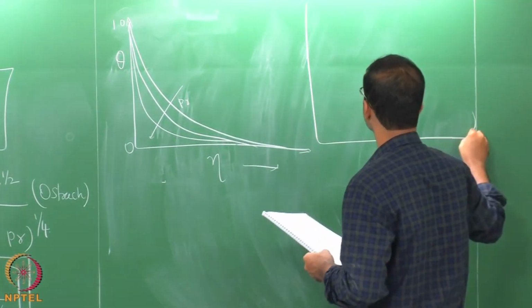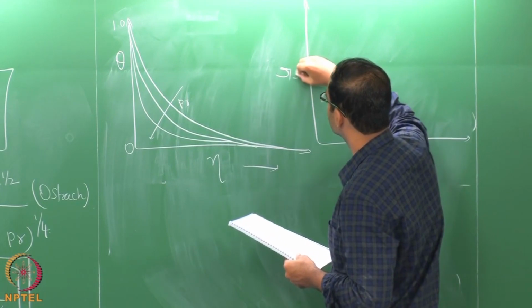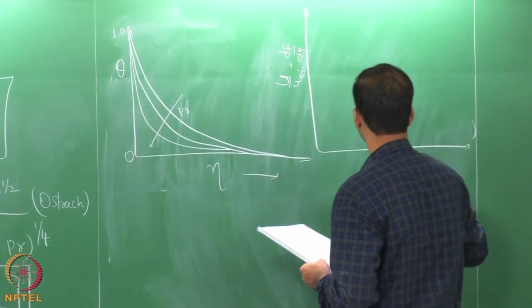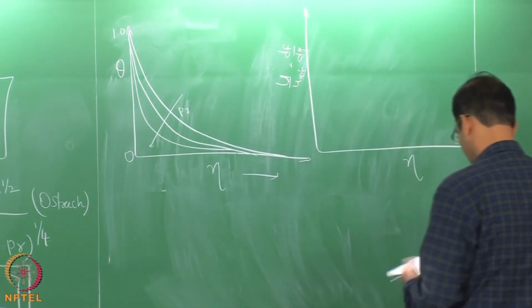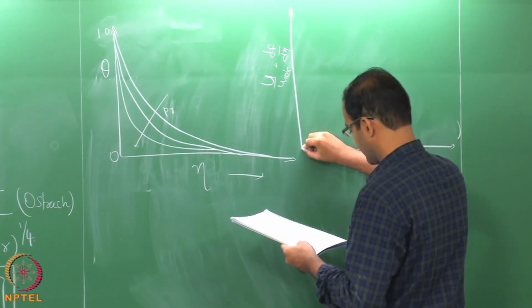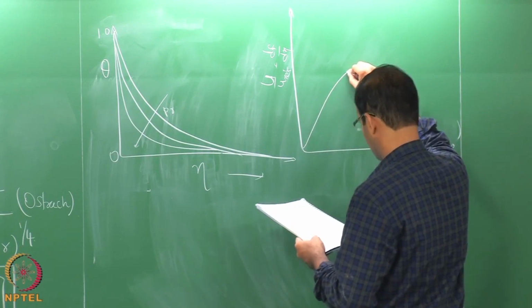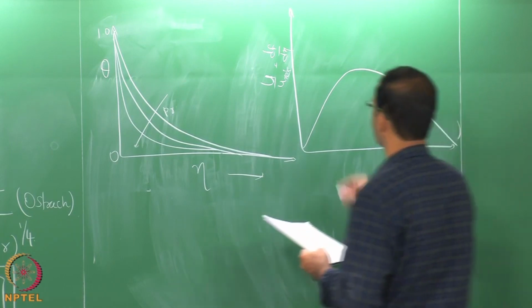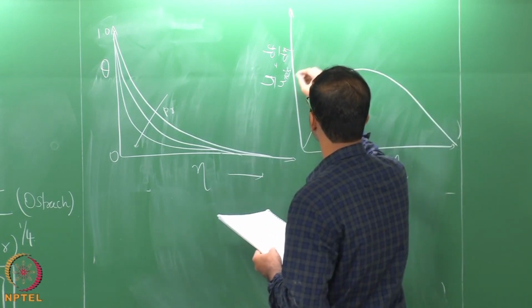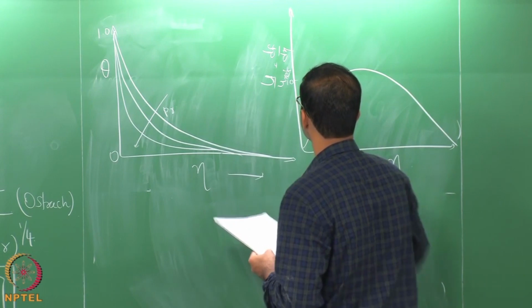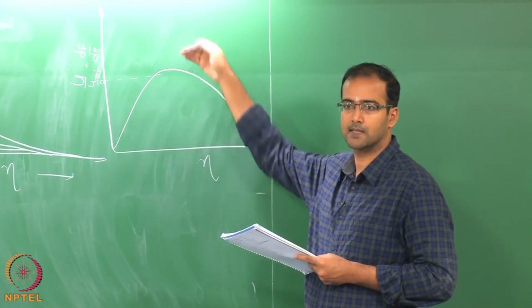Similarly, if you plot your u by u ref, which is nothing but df by d eta as a function of eta. Okay. So, this also shows a functionality with Prandtl number. So, you find something like this. It reaches a value depending on what you take as your u ref. Suppose somewhere here it is your u ref, it reaches 1 here, okay.